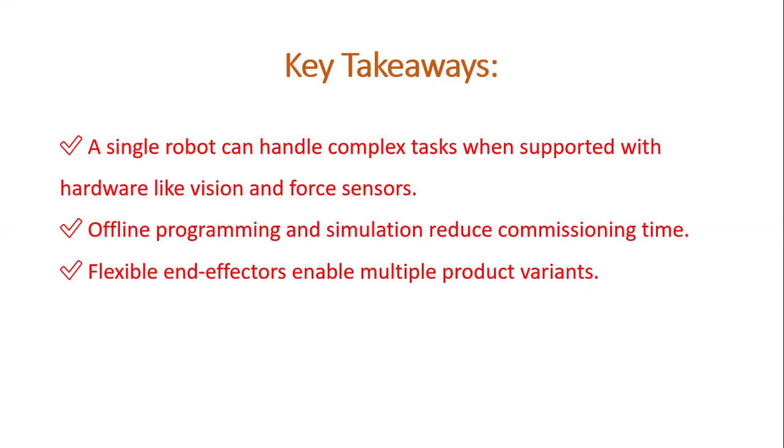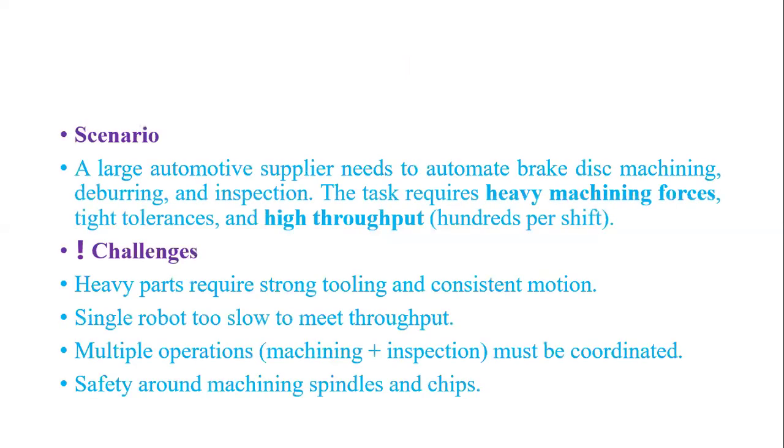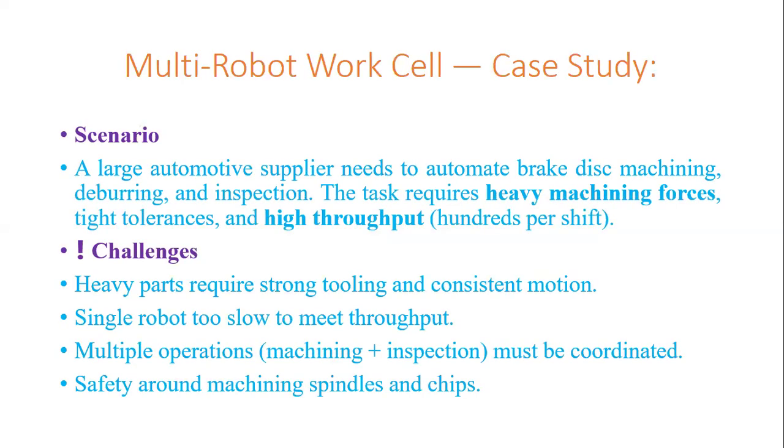Now, in comparison with this, we are now going to discuss the multi-robot work cell type assembly system. So normally the multi-robot work cell is commonly used for mass production. When you go for large scale production, say consider an automotive assembly shop, in that case a multi-robot work cell is considered to be a preferable choice to perform all the set of sequential activities.